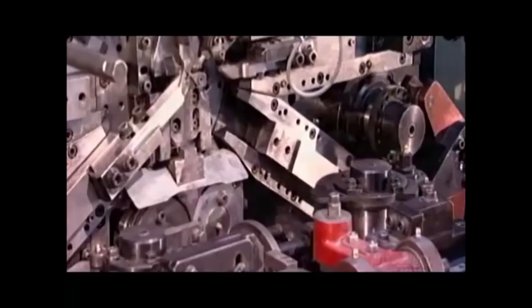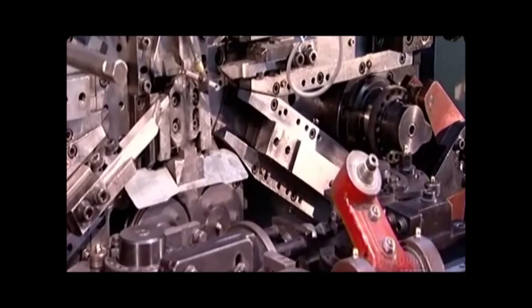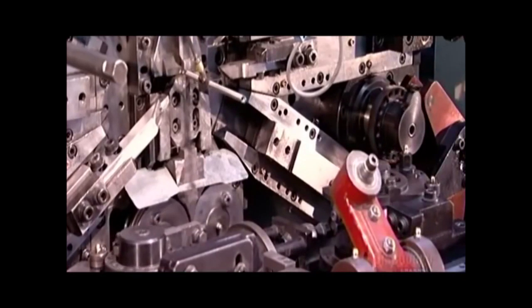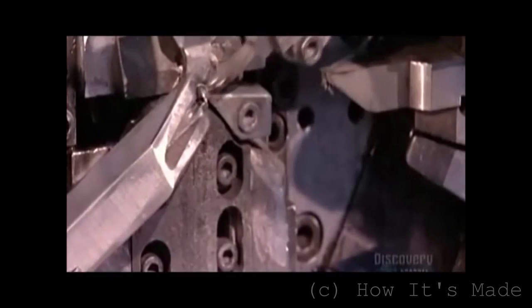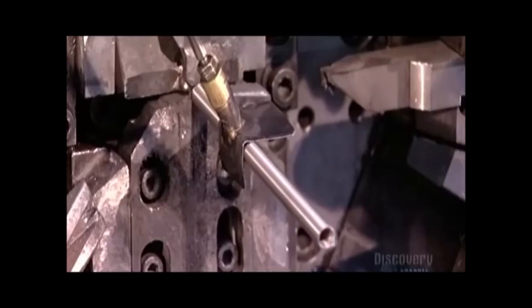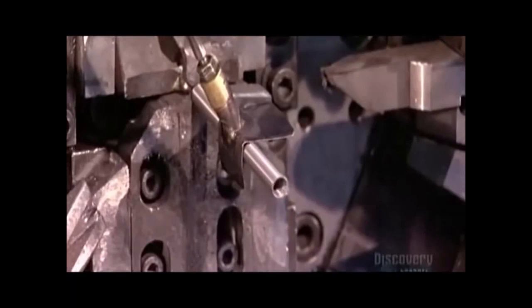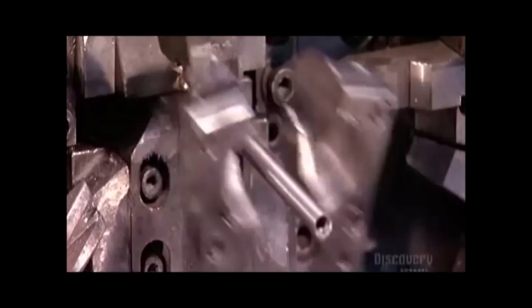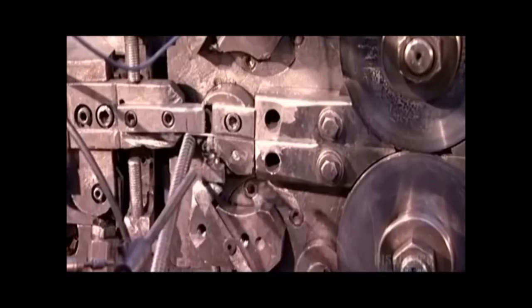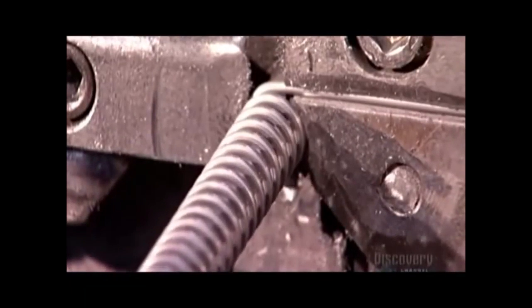Forming the springs. The coil spring is made from metal that has the ability to withstand a constant pressure and release and still maintain its shape. Coil springs such as the follow spring are wound around rods and heat treated. The coil spring material is wound around an appropriately sized rod and then heat treated to produce changes in the metal's characteristics. Changes that give the metal its elasticity. The heat-treated coil can be pulled apart and pressed together with reason and still return to its original wound-up condition.